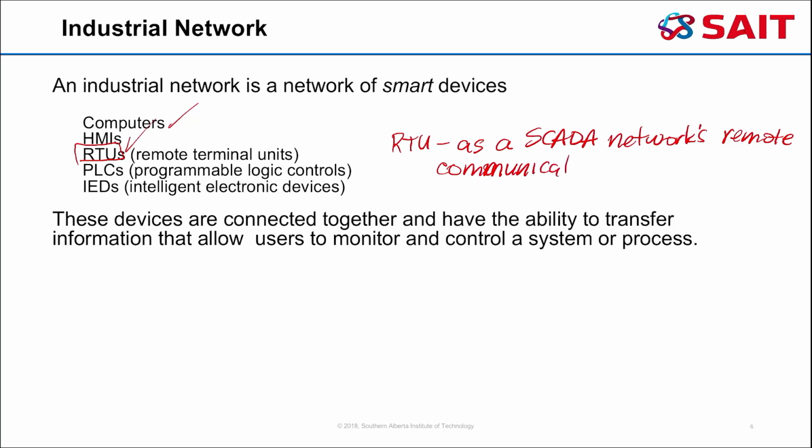Its primary job is to communicate with all the local area components in a substation or generation plant and so on, to communicate with all the local devices using their specific language or protocol, using their specific mediums or physical protocols, and collecting all that data and then reporting to a higher level, or the master, or the MCC, the Master Control Center.